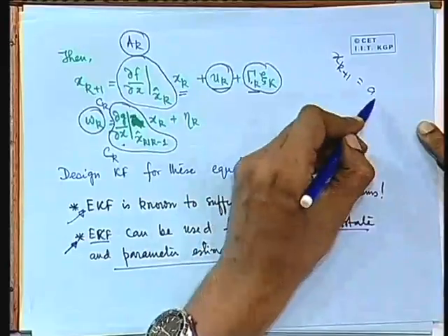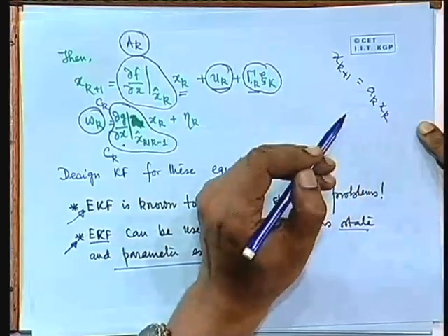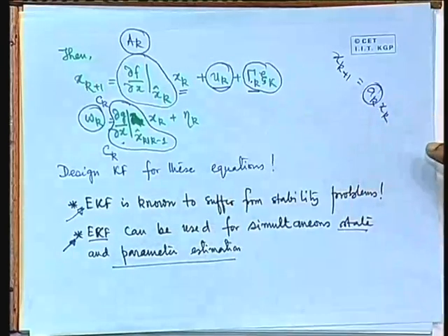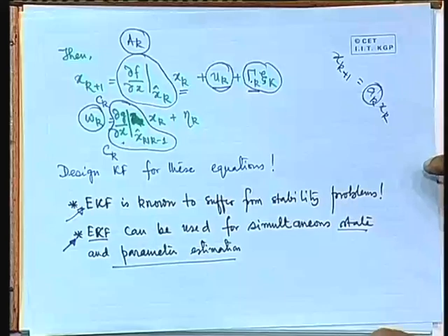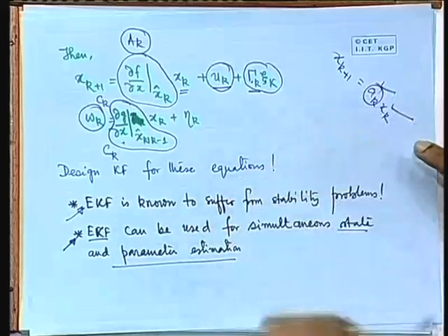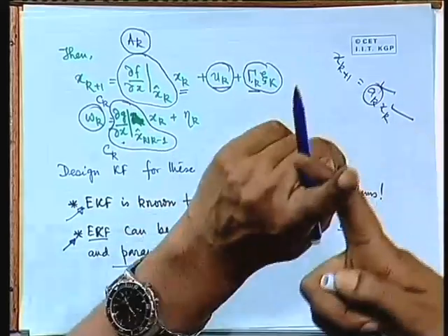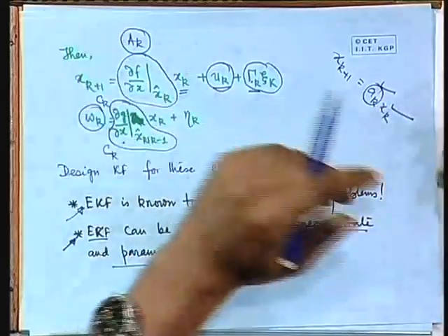So then what do you do? Then you have to simultaneously estimate the state and the model parameters. Obviously, the model, for example, xk plus 1 is equal to ak xk, is linear if ak is known, but completely non-linear if ak and xk are both unknowns, because you have a product of two unknowns. So it is a non-linear model.